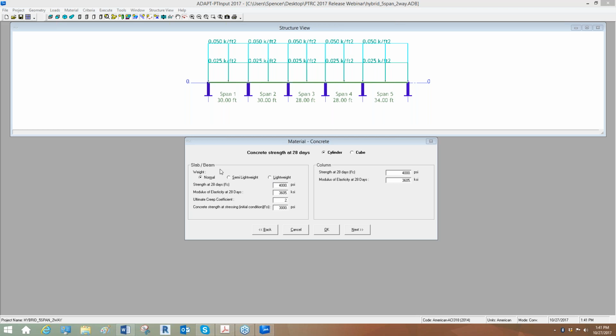The question is, in Builder, is top steel considered in deflection, and how in a cantilever? The top steel is considered in a way such that when the program calculates the cracking moment of inertia, it's a function of I crack, the cracked moment of inertia, which takes into consideration the position and the location of the steel.